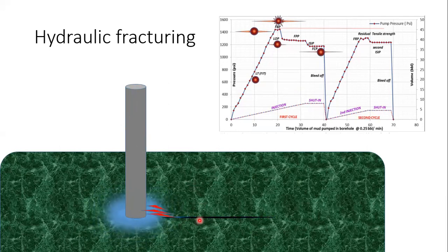So right now the fracturing fluid is entering into the channels which were generated by perforations. The perforation itself will create a channel, but the flow is not enough through it. You can see the very narrow channel generated over here, and we started to inject fracturing fluid into these channels. Once the fracturing fluids enter into this channel, the pressure is expected to rise.